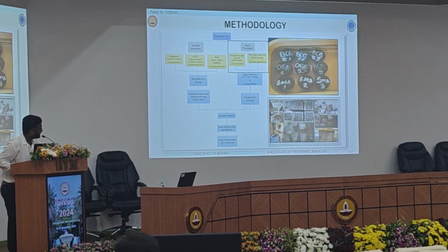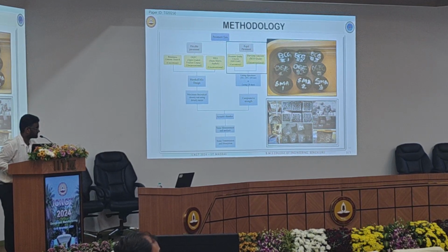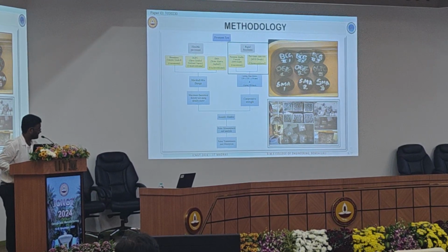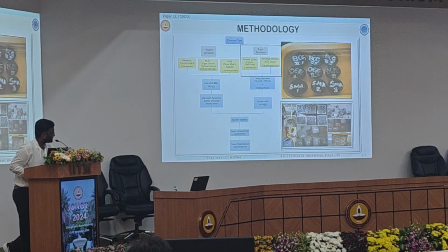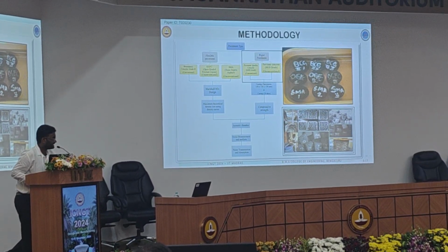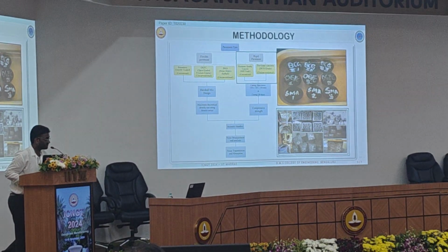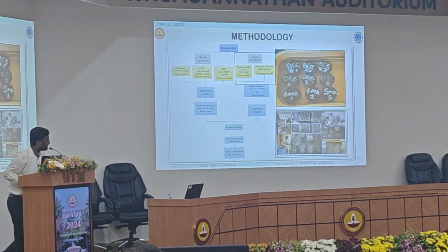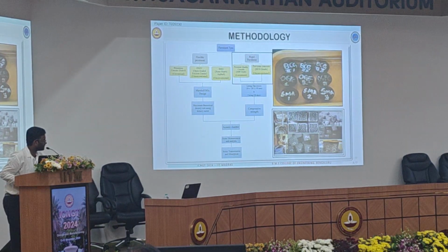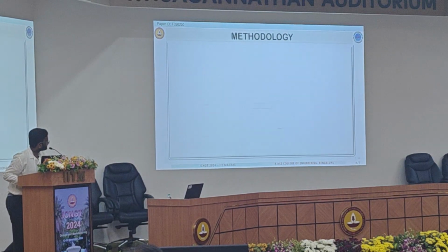They were cured for 28 days under water, and then compressive strength testing was carried out to check how stable they are. Acoustic evaluation was done, and noise measurement and analysis was done. Noise was captured for 30 minutes for all the specimens. Three specimens of each were cast, and they were tested for noise transmission and absorption.